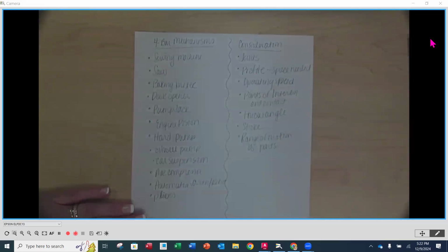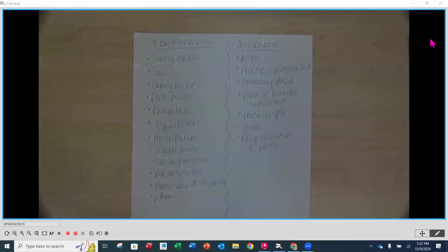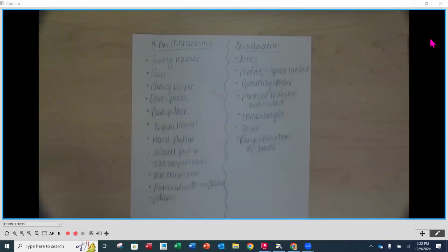So when we have a final operation in mind, usually the output motion is where we start. For instance, what is the stroke that we want to achieve? What is the throw angle that we want to achieve? Then depending on the other elements you talked about, the space relationships, how much or little space we have is going to start to dictate the types of mechanisms. We talked about 4-bar mechanisms, but at some point you may even consider chains, belts, or gears to get something done as well. Maybe you need to gear down or slow down a speed off of a motor.